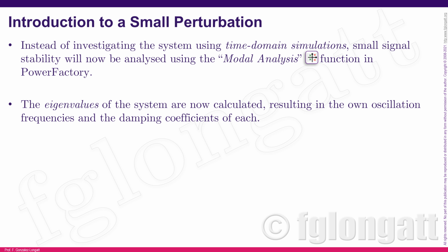When we use the modal analysis, the good news is that PowerFactory is doing several important tasks for you, okay? Because internally, PowerFactory is calculating the state matrix. When you use the modal analysis, you must be careful because PowerFactory is defining for you the state matrix, and this state matrix defined inside PowerFactory is a numerical state matrix, okay? I will not go into more detail, but you must understand that when we are using software like DIgSILENT PowerFactory, there are different ways to define the state matrix. One of them is using numerical approximations, okay? And then PowerFactory calculates the state matrix for you.